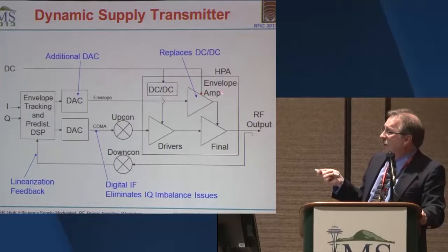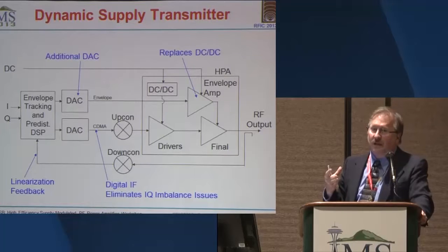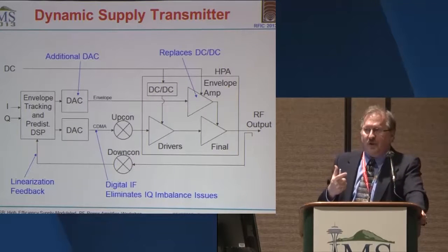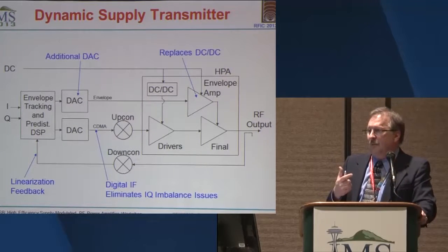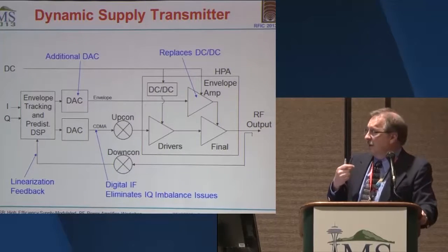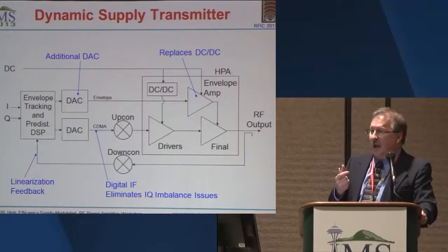The other thing is our envelope amplifier here. Most of my results will be based on a base station sized envelope amplifier, which has a peak capability of about 100 watts. It's typically supplying to the RFPA 60 to 80% of that, depending on how it's tuned up and the specifics of the waveform. And then the RFPA in general is running anywhere from 50 to 80% efficient. So depending on the specifics of the waveform, that's the general configuration of what we've been working with.